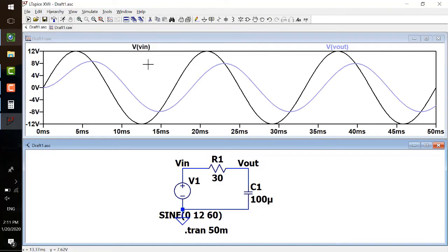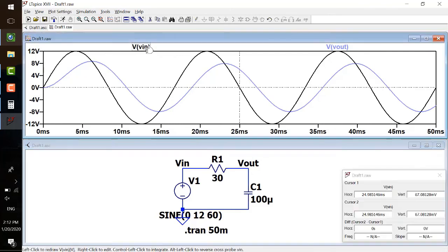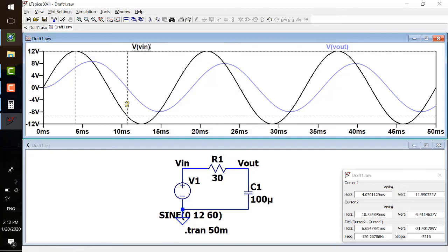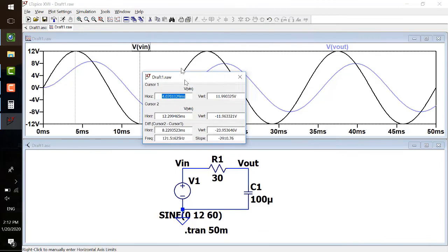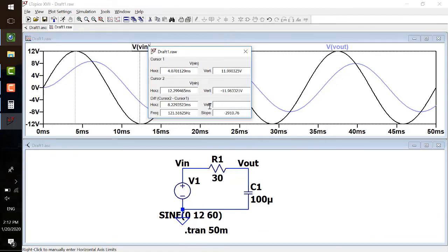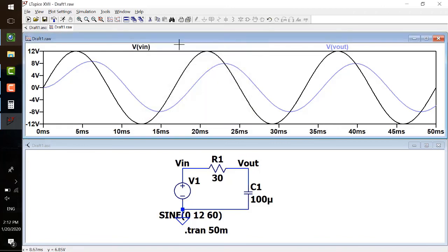How do you want to test the amplitude? Yeah, two cursors. Double click V in. So got 2. Probe the top here. You know it's 24 volts, right? Since you assigned that, you designed that 24 volts. See, two cursors, and you look at here, 23.95 something volts. You cannot make it 100% perfect here, so it's 24 volts.